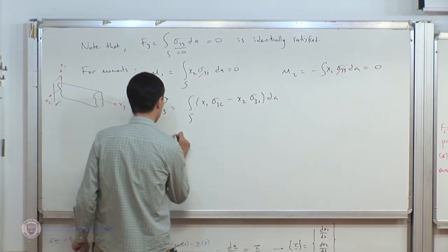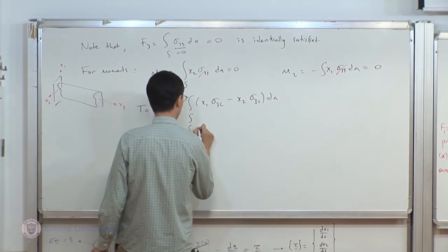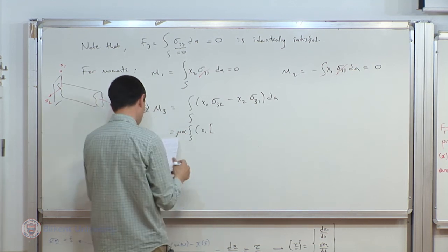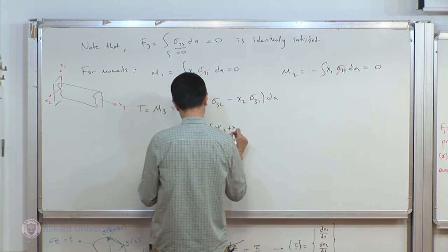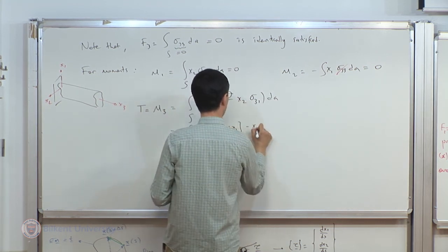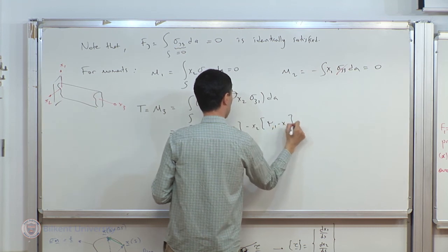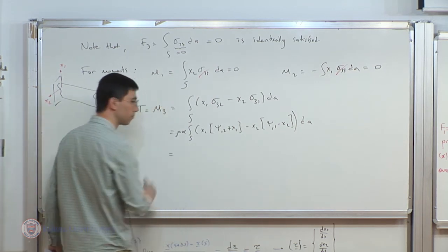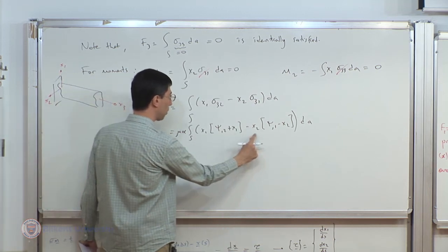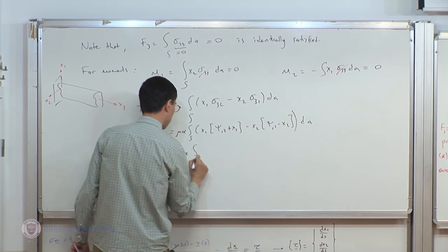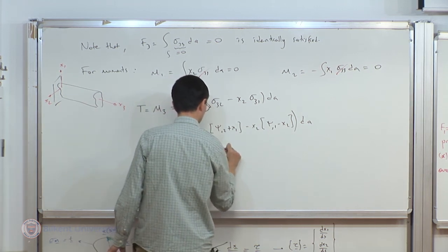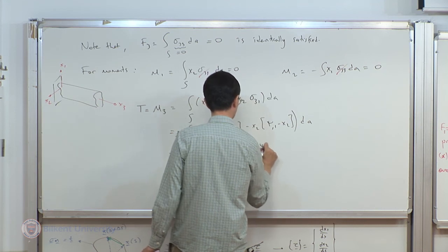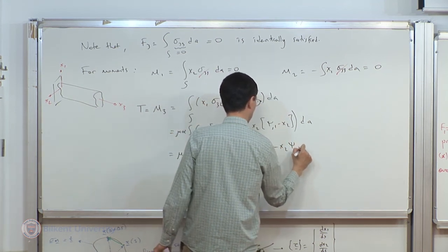Now, we've indicated the components of the stress several times. Let me plug them here. So we have here x1. I'll take mu alpha outside because it appears in the components. So psi comma 2 plus x1. And then minus x2, psi comma 1 minus x2. So I'm just going to put together terms, x1 squared plus x2 squared, plus x1 psi comma 2 minus x2 psi comma 1.